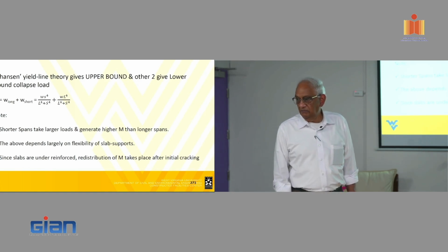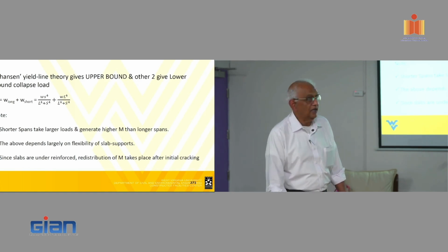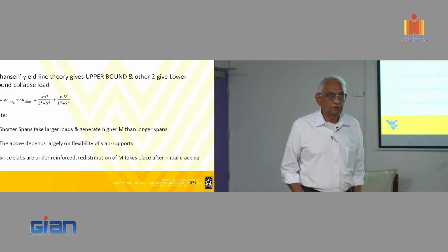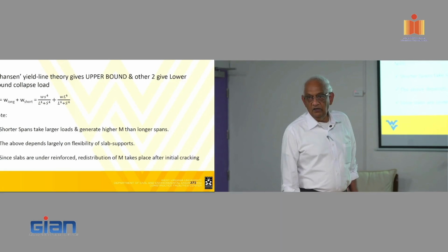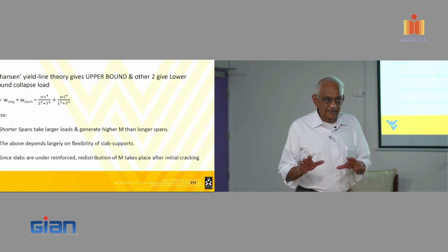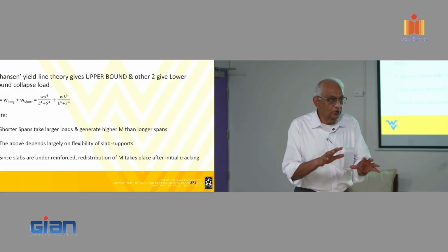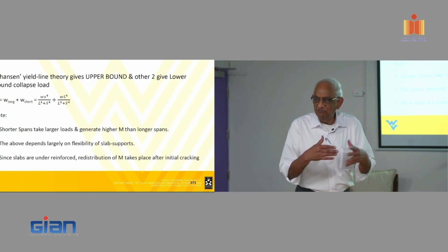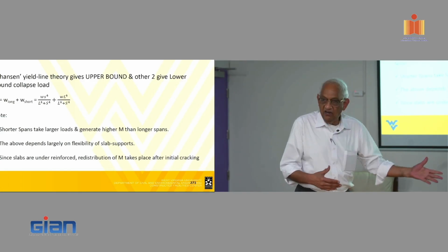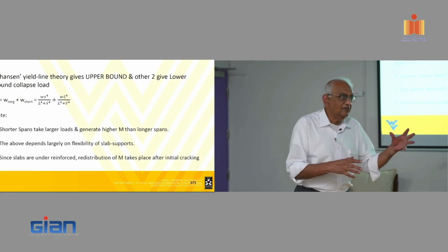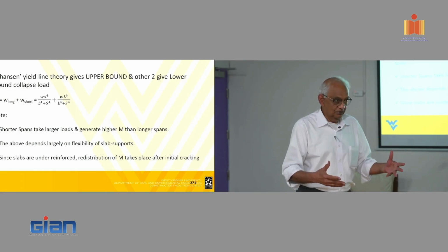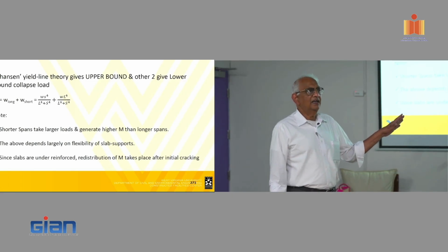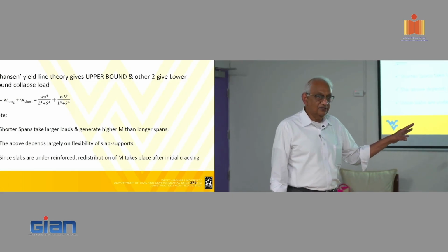Do you get it? That's what we are talking about. That's the last one. So redistribution takes place. In the tug of war, I don't know how many of you participated, everybody carries the same pull up to a point. The weak guys, after a point, cannot pull any more than they were. So the strong guys take over. Even that is what is called redistribution. Same here. Higher the EI value, higher the attraction of the moment.